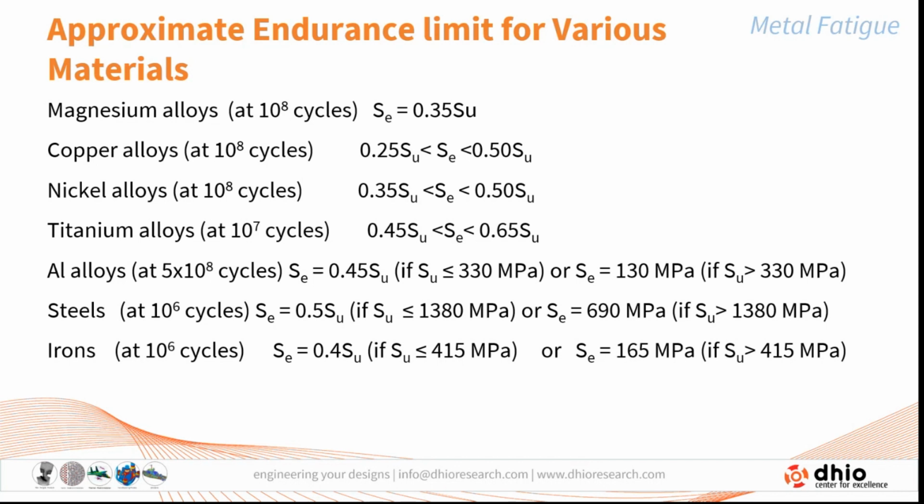And again, you cannot say that it is always going to have the same amplitude in each and every cycle. If the variation of the loading is random in nature, then we have to adopt statistical methods to make it a narrow band of data which has to be calculated.